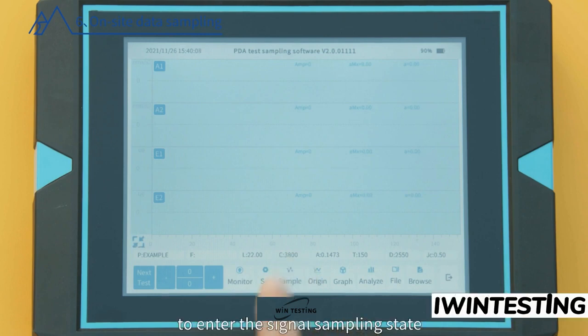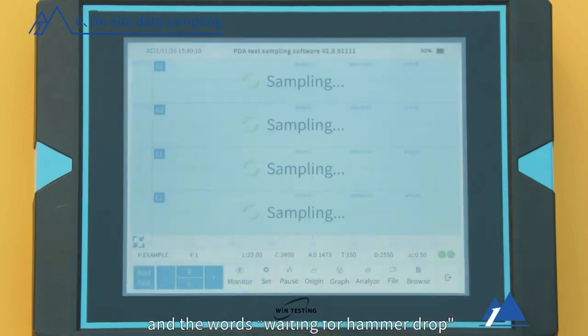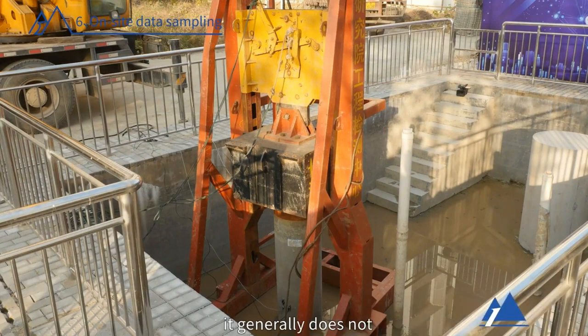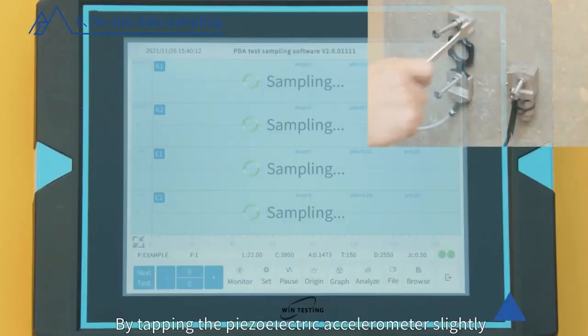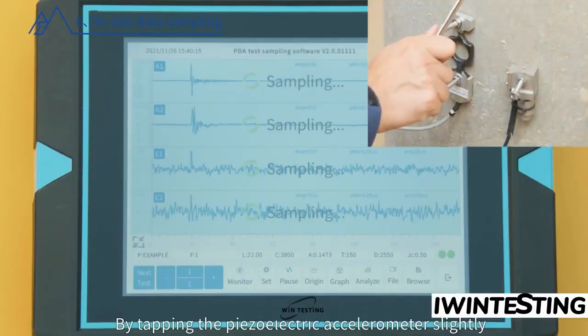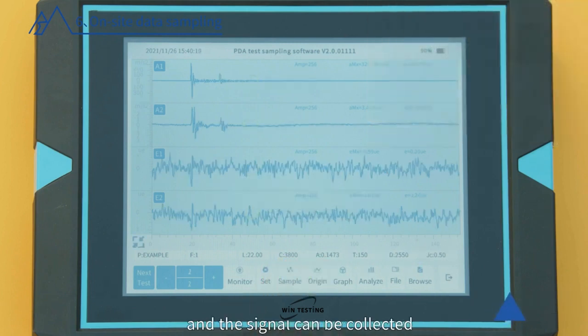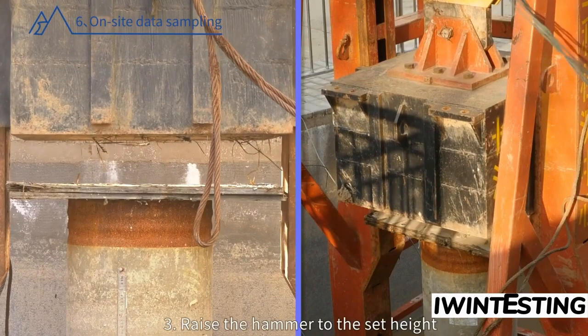2. Click Sample to enter the signal sampling state, and the words "Waiting for hammer drop" are displayed in the curve area of each sensor. Although high strain is a non-destructive test, it generally does not have multiple hammering conditions. By tapping the piezoelectric accelerometer slightly, it can be confirmed whether it can be triggered normally and the signal can be collected before the on-site test.